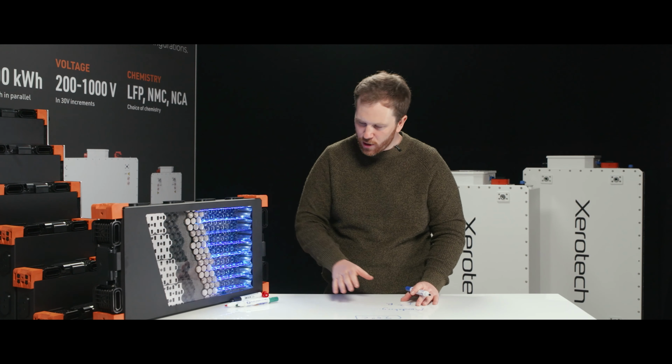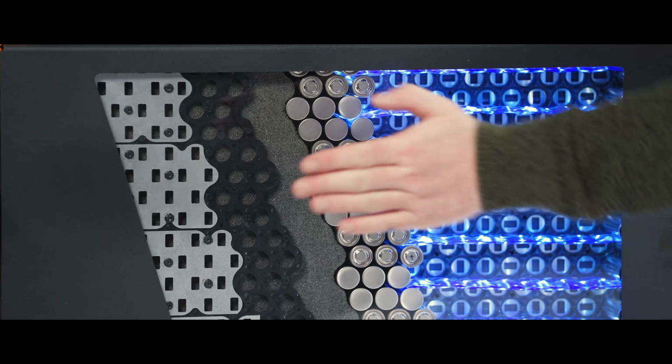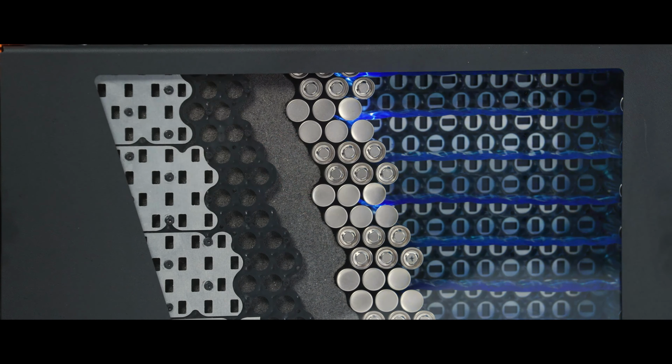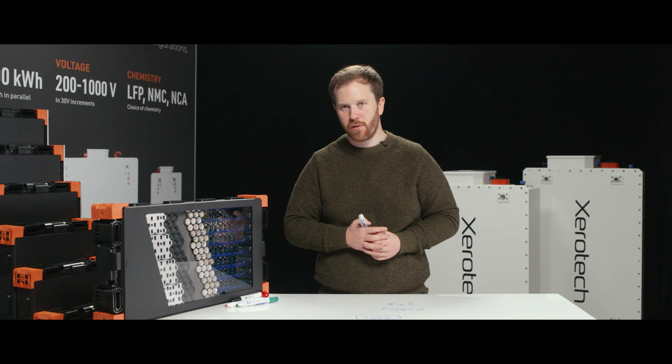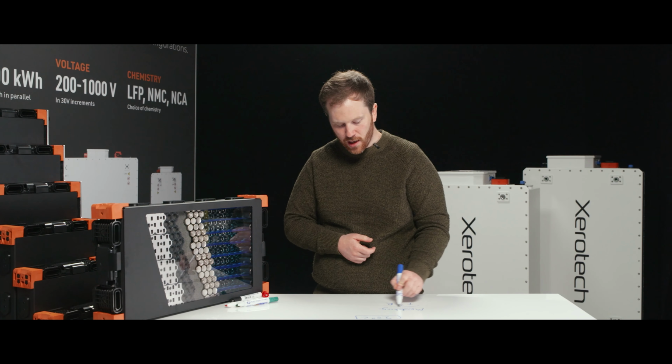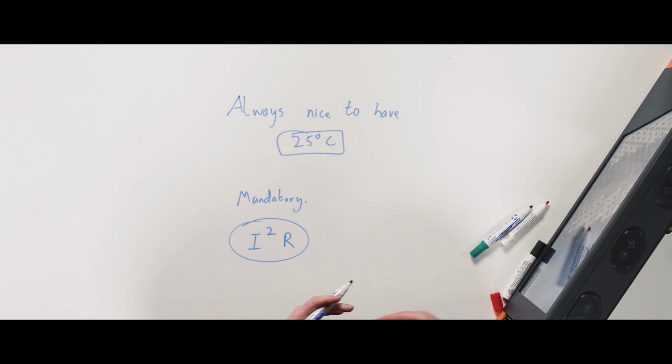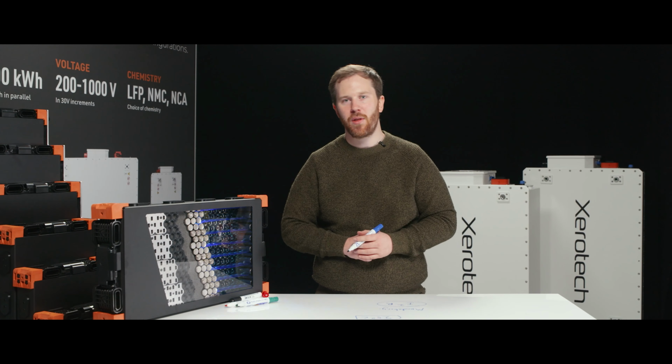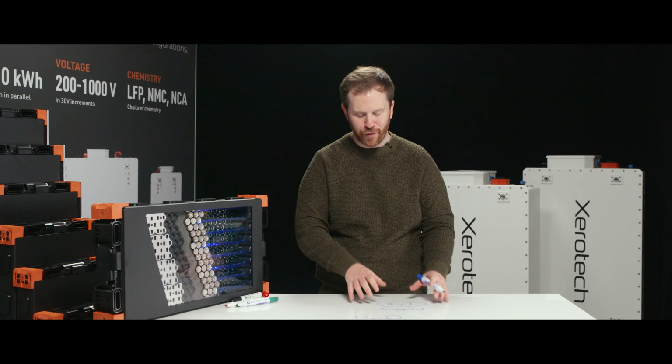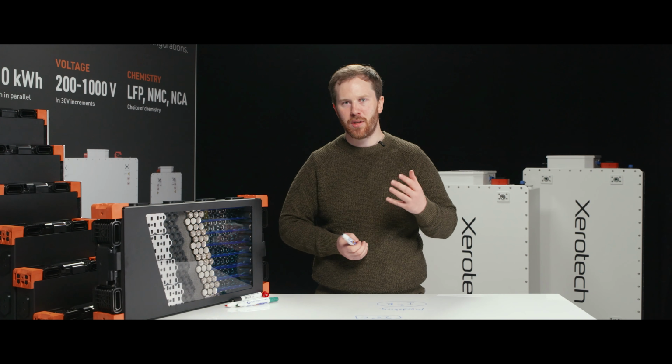So higher discharge rates, whether it's flowing into the battery, charging, or out of the battery, doesn't really make any difference. It's still largely dominated by this equation. So there's not a huge difference between charging and discharging of a battery pack from a heat generation perspective. There are some minor chemistry things that make it a little bit different, but fundamentally it's mostly the same. It's just about the rate.